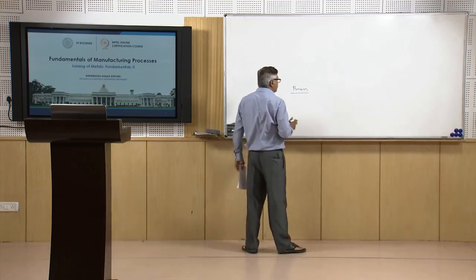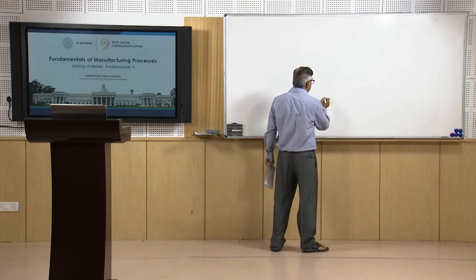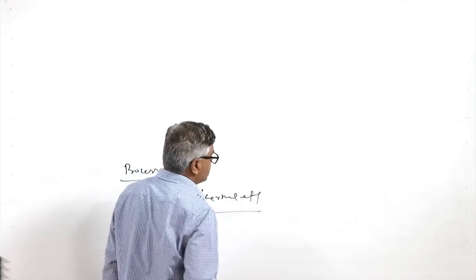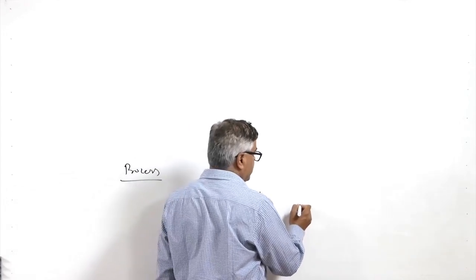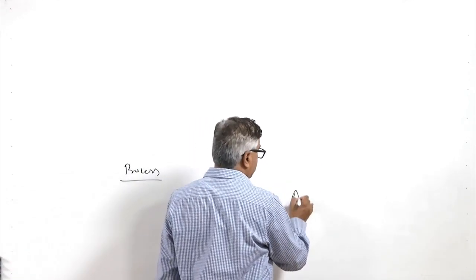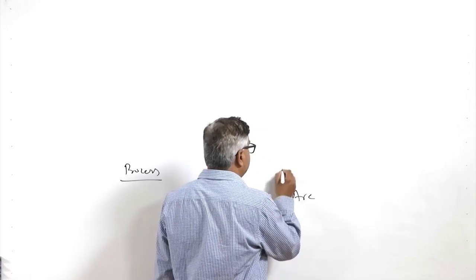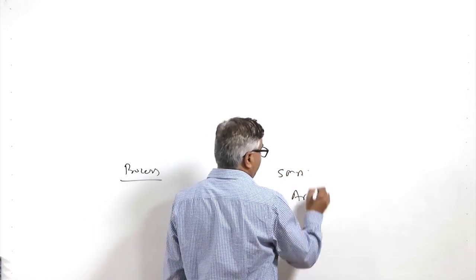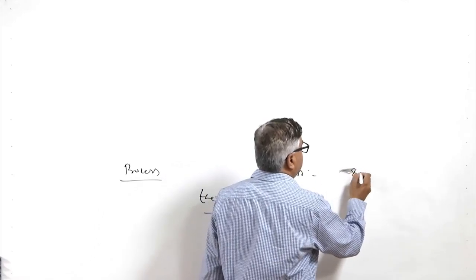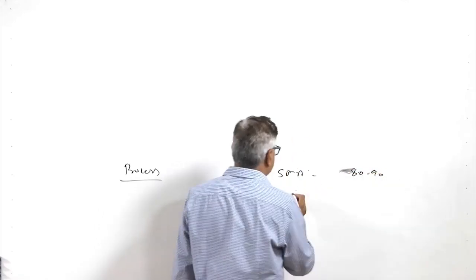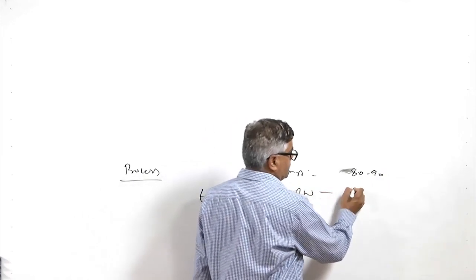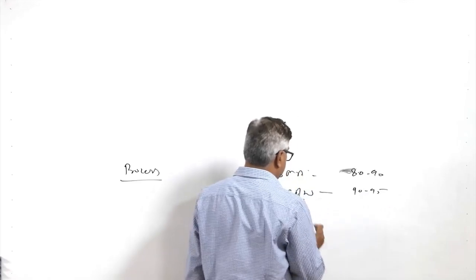Normally, if both are clubbed, we call it the thermal efficiency of the welding process, which is different for different processes. For the simple shielded metal arc welding process, it may be 80 to 90%, but for the submerged arc welding process it is 90 to 95%.